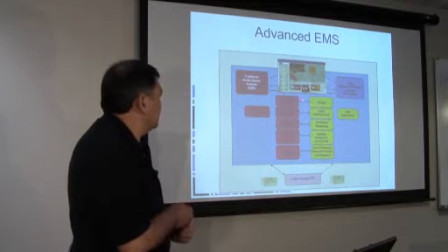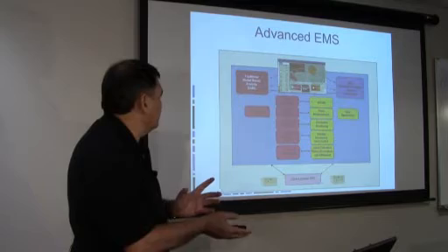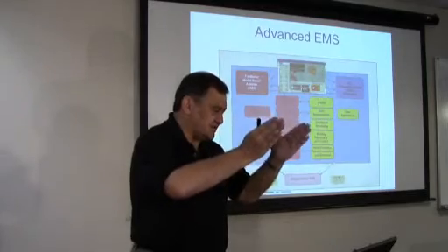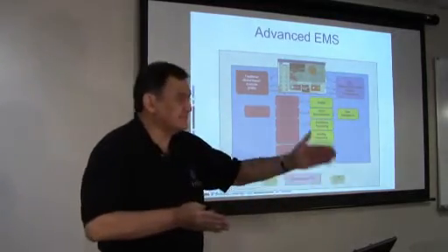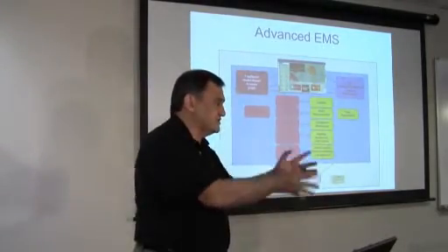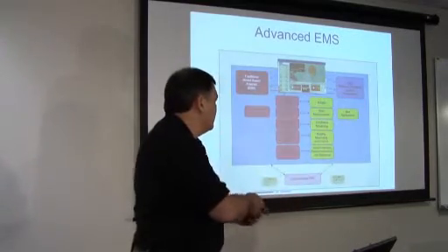and we'll get into more detail. They are much more sophisticated. They are opening up a whole different need for training. In the past, we simply gave the operator these limits, and we said, keep the power flow within these limits and everything will be safe. Now those limits are very conservative because they're based on offline studies. In some cases, the power system may get into a state where events may happen which they haven't been able to pre-study. So it's much more important to have the applications running right there to determine what are the safe limits for moving power across the system. That's basically what these applications are doing.